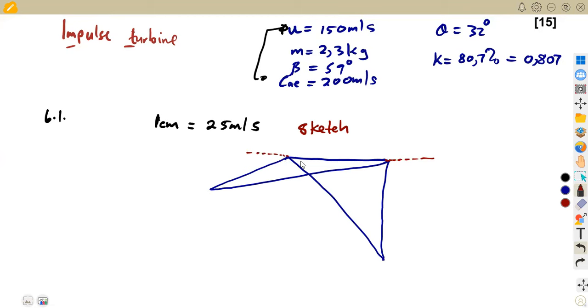We have the value of our blade velocity, that is 150 meters per second. You see this thing of working with engineering science. Now I'm taking you as the initial velocity. No, that is our blade velocity. All right, if we consider this theta, that is the inlet at the blade, the blade inlet. You're supposed to know each and every part of your diagram. So this is the blade inlet, which is this one. So we've got our theta, which is equivalent to 32 degrees.